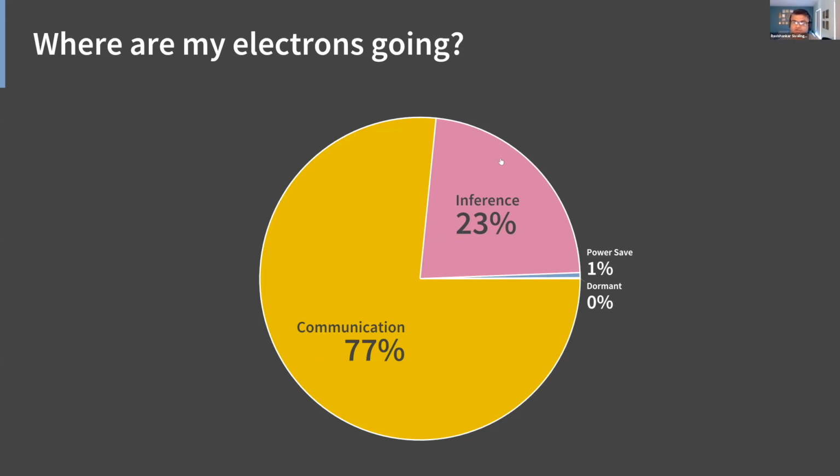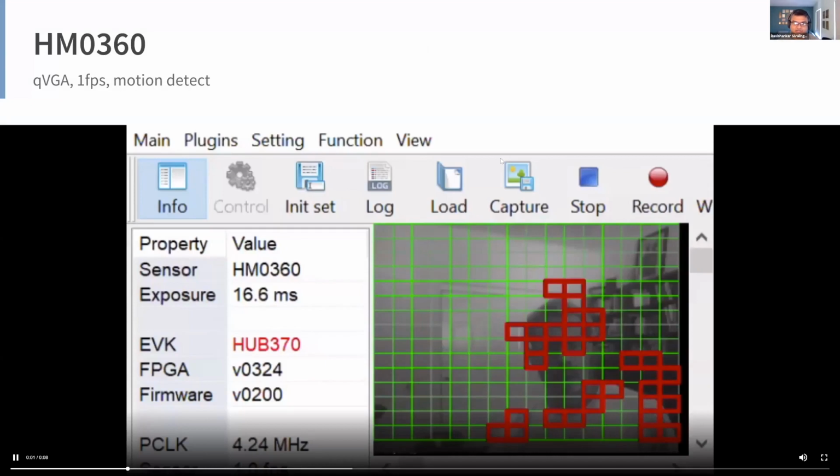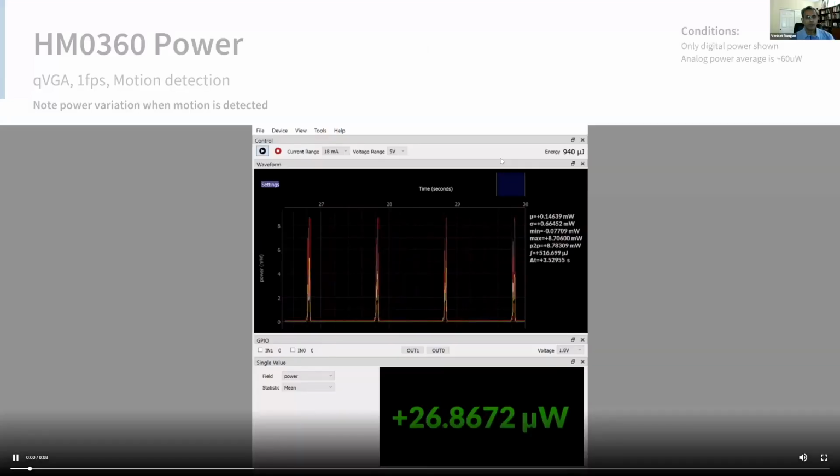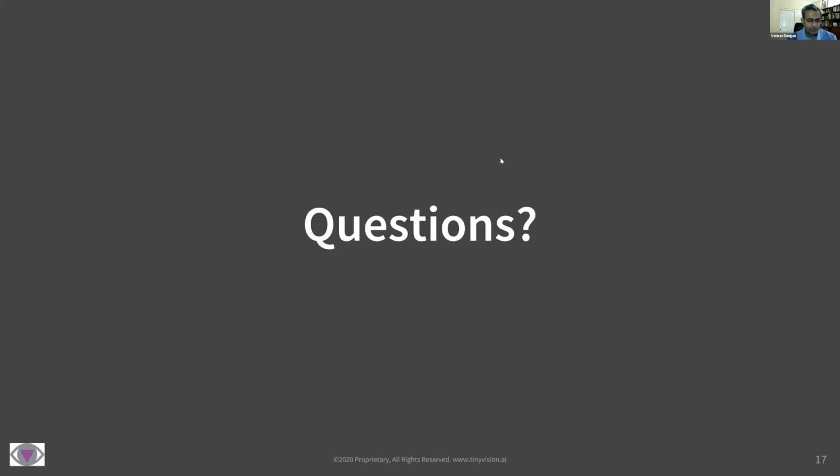Could you briefly touch upon the multiple tiers of CV algorithms that you mentioned? Sure. Think about it this way, right? You have the possibility of an image sensor having motion detection. They tend to be rather crude, not as sophisticated, because that's really what you need, something basic that triggers. It may have a high false positive rate. Then once that triggers, you send the image over to the processor. That takes energy, so you want to minimize that. And that's the reason you have in-sensor motion detection.